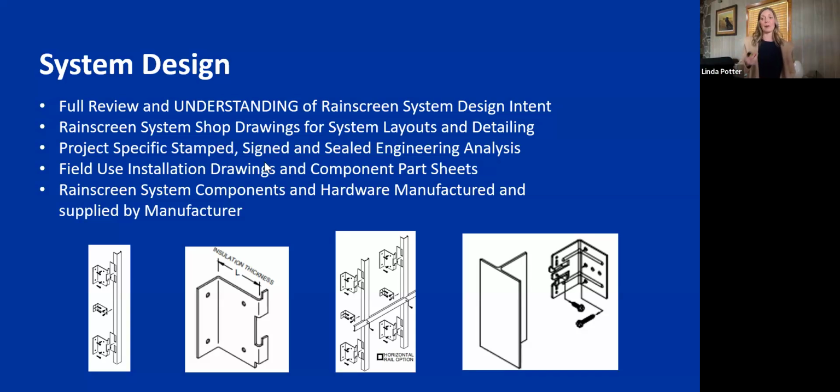And unfortunately, some of this stuff ends up getting contractors have done a job that did this spacing and anchored in this way, and we assume that that will work on this project over here, and we don't actually do those specific calculations for this job, when in fact we might have completely different parameters and open ourselves up for problems. So ensuring that that actually gets done is going to be necessary for your client's long-term success of that building.